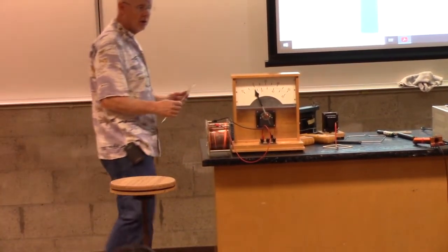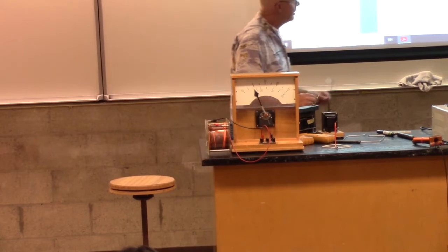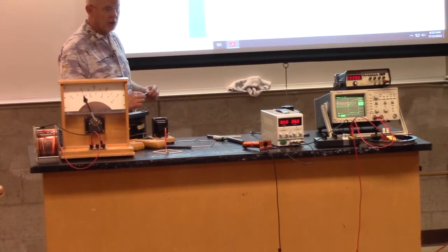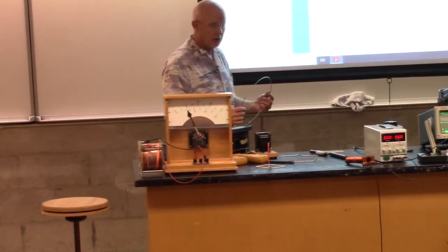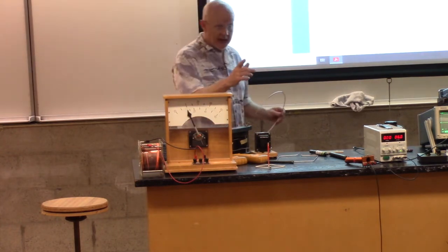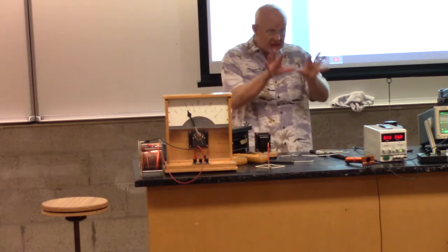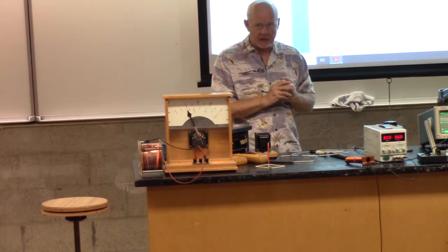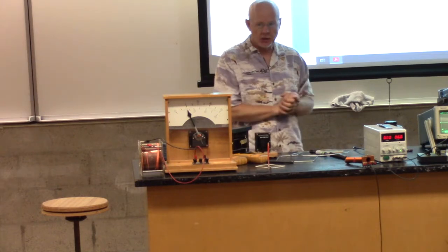Yeah? I want to make sure I understand this correctly. So if, I guess in this case, another coil in the system, specifically the primary, changes, then the second one, its reaction is to change magnitude and direction? Well, its reaction is to keep the flux the same. That's Lenz's law. Opposes the change.